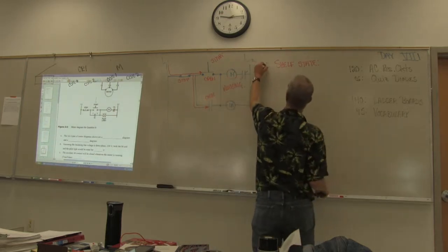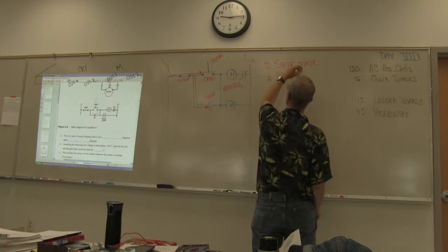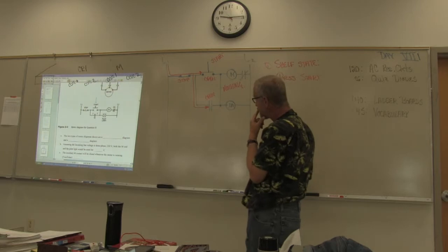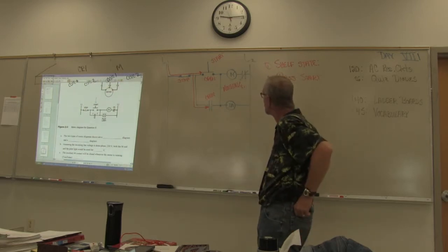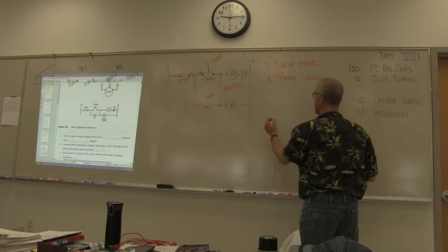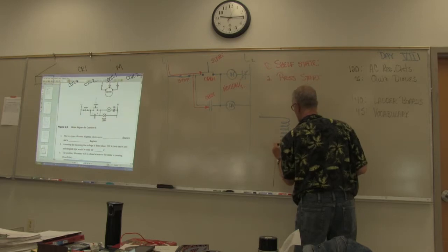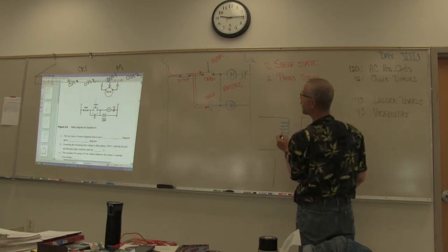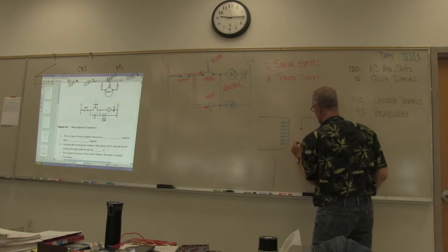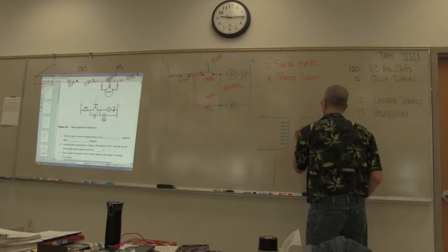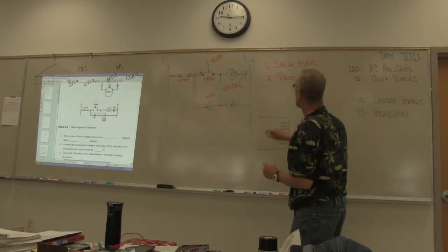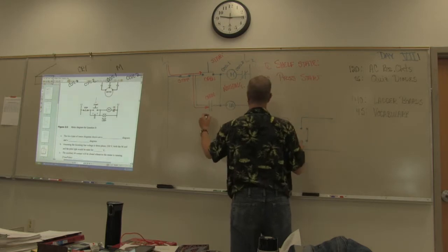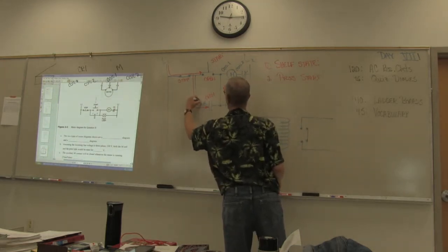Okay? Number 2, press start. But I guess I don't understand how the contactor itself is actually activated, because in my mind, the way it's wired. No, here's what you have. Here's your contactor. Remember this? We have a coil, and in this case, you have a normally open contact, right? Is that the only thing we have in there? Yes. The only thing that we're using is a normally open contact, which looks like this. Okay, here's our coil. And here is our contact. Let's just call it MA and MB.